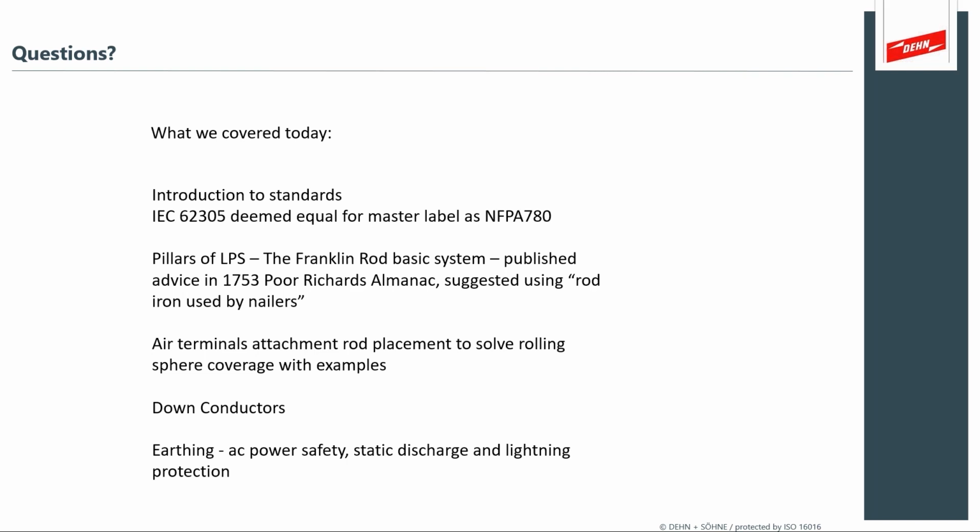When we say interconnected mesh, that's the mesh of dedicated conductors for the purpose of lightning protection. So that's a 10-meter mesh. If you're not using the system as part of your lightning protection, it can be a 20-meter mesh. And that builds a nice, clean, equipotential bonded system so that you reduce touch and step voltage. I believe that's the correct answer for your question.